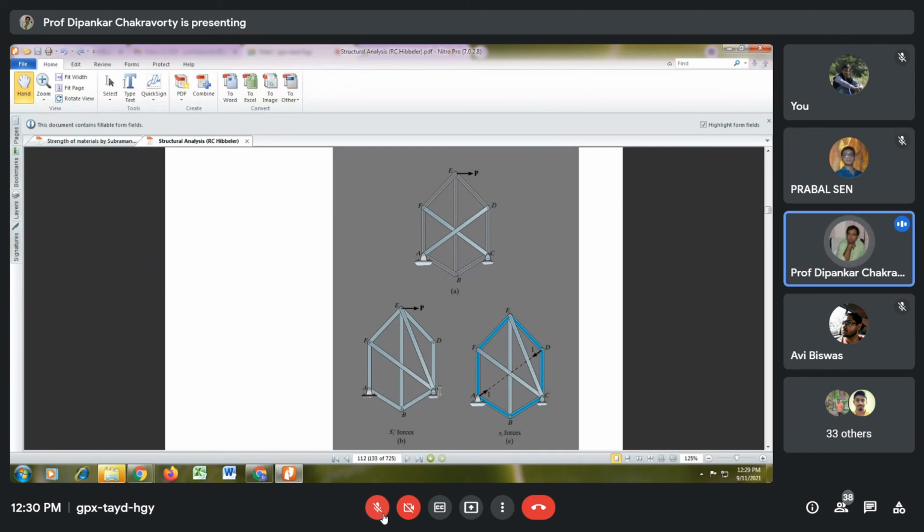Acha, we know that to maintain the stability of a truss, all the members should be a part of a basic triangle. So if I withdraw the member AD, I'm not withdrawing really. I'm assuming that the bar force in member AD is X. They have given it as 1, I do not know why. Anyway, I give it X.